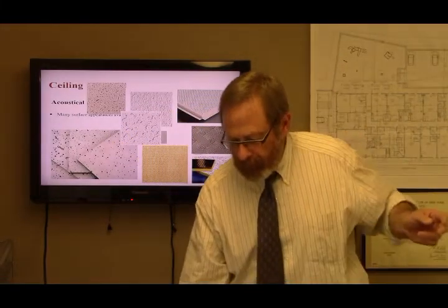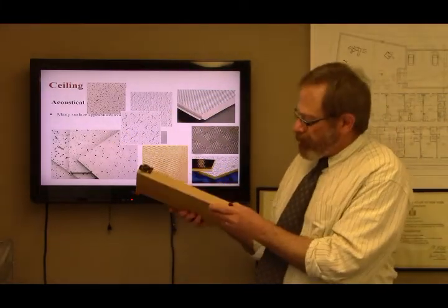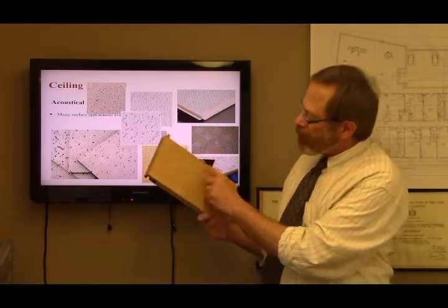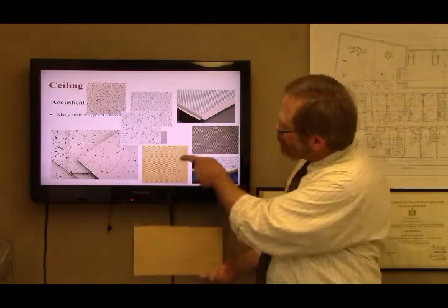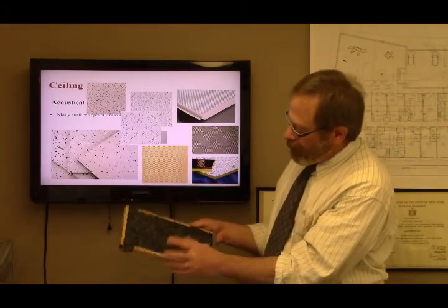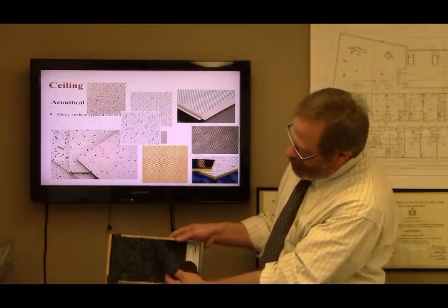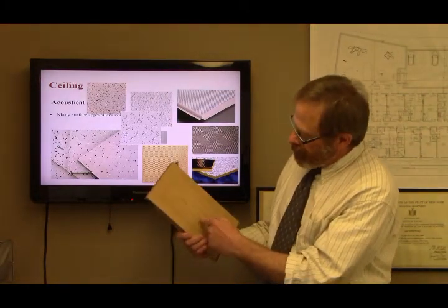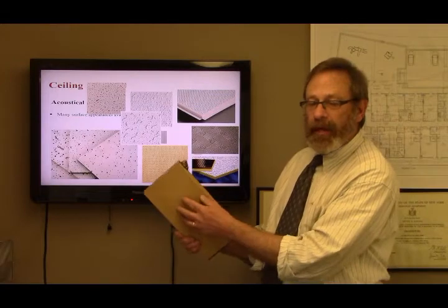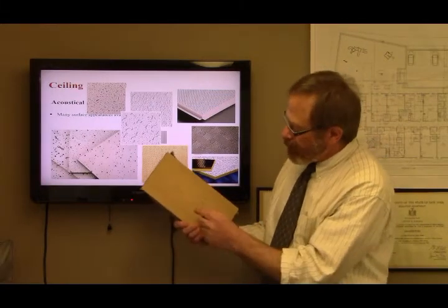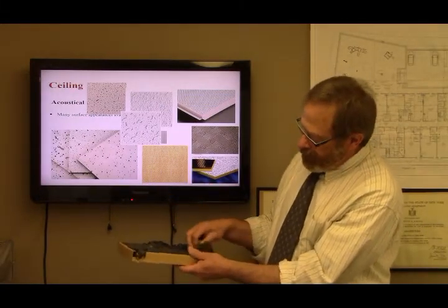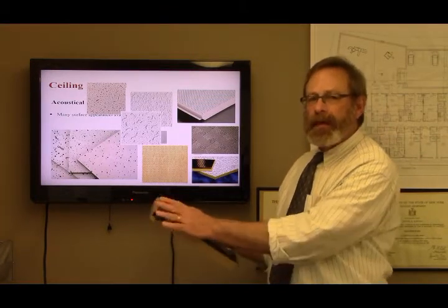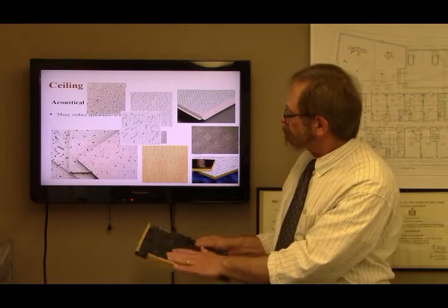This is a wood simulated metal acoustical tile. You can see the holes in it, hopefully. Just like that, it has holes in it. It's also available with sound batting, so that once the sound penetrates those little holes, we don't want the sound to reflect back into the room. We don't want a silent piece. Through those little holes, the sound gets sucked up and absorbed within that piece of bat insulation or sound insulation.